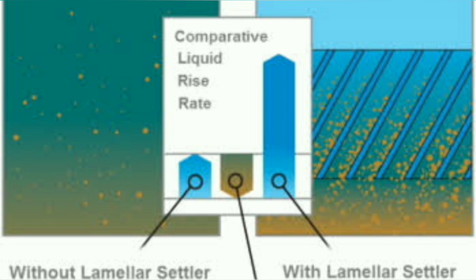And also, due to their high efficiency, the size of the basin can be reduced to around half when we compare with regular settlers. The disadvantages with this are that it needs a special design and also installation. This is not like regular construction of a sedimentation tank. Some skilled supervision and also labor work is required, and also the initial investment for both plate settlers as well as tube settlers is quite high.